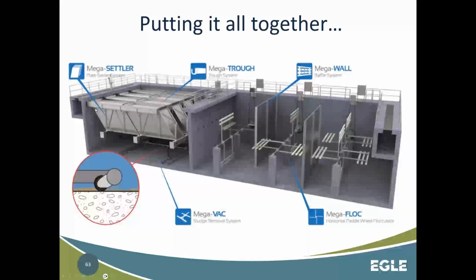Similar to a conventional settling basin or even a clarifier for that matter, there is still going to have to be a sludge collection component. And that is being accomplished in this system. Looks like they have those vacuum headers that we saw in some of the others, where this is going to be able to travel down the bottom of the basin, and it's going to rely on the head pressure from the basin to push the sludge in.